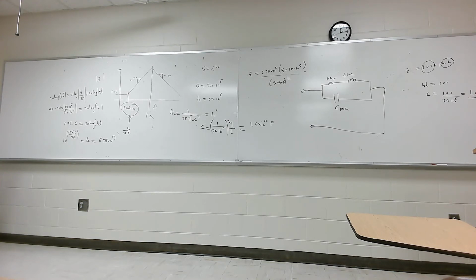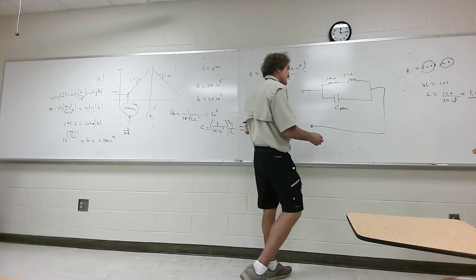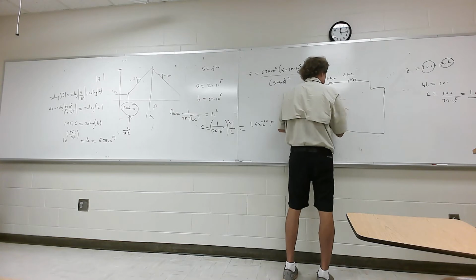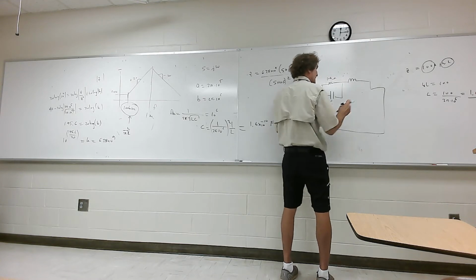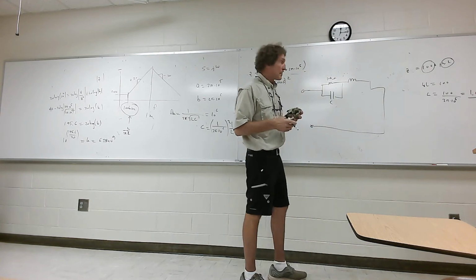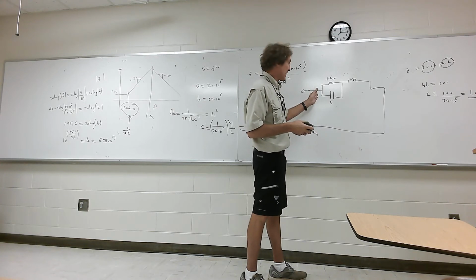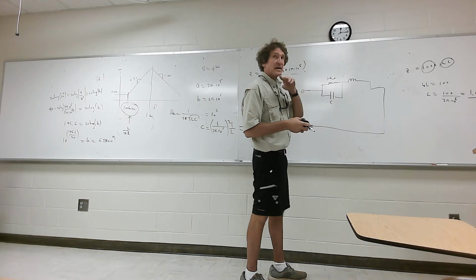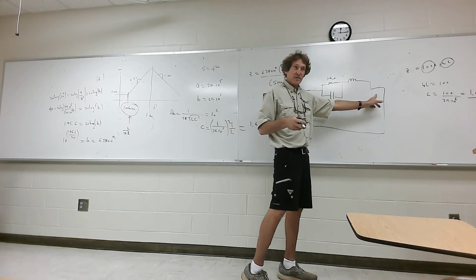Mine is a different circuit layout than theirs. I put the capacitor in parallel with the series combination, and what he did, he can get the same thing, basically. He took this right here, and he's using this to get that. It's going to do the same thing, it's just that the capacitor is now just over the 100 ohms. That's not a true inductor. I mean, the inductive capacitance is across the entire thing, if you look at the model for it.